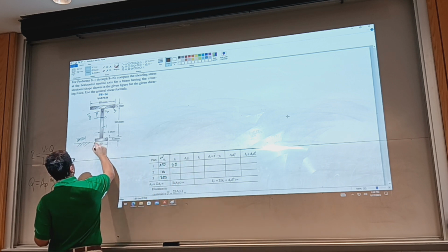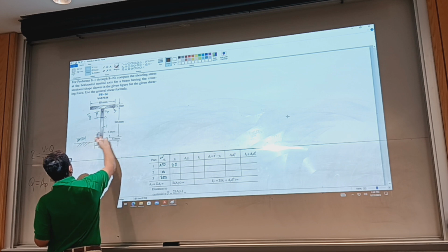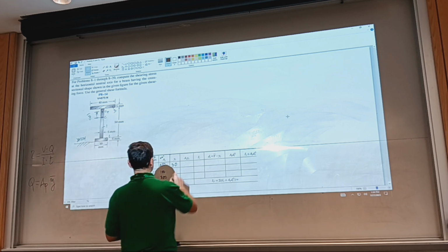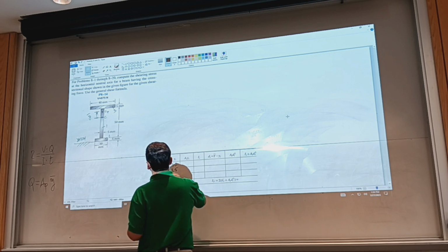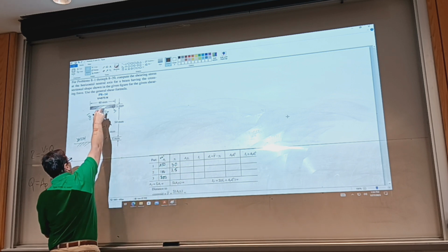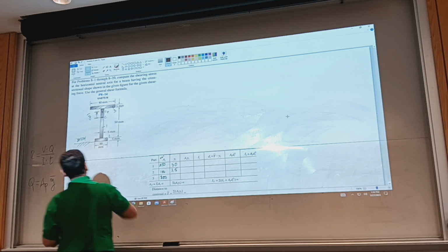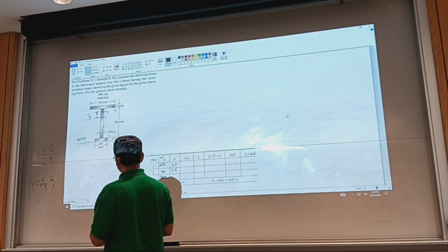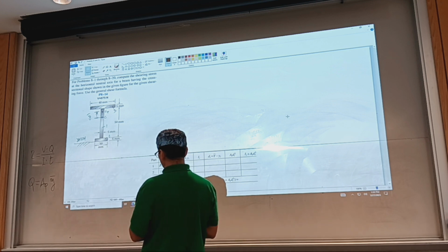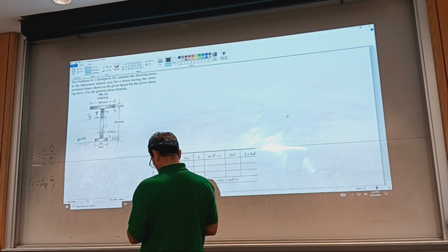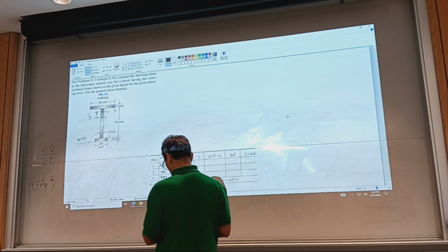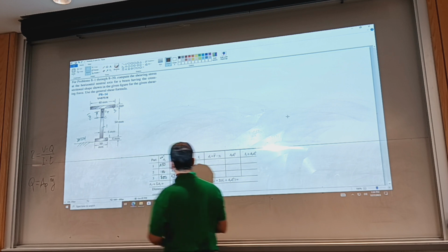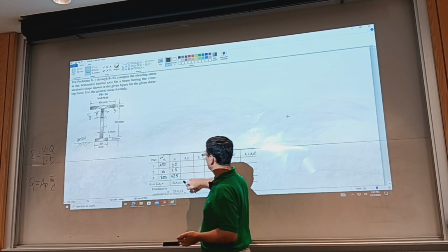For shape 2, the small horizontal rectangle, that's half of 5, that's 2.5. And from the datum all the way to the centroid of the wider flange, that's 50 plus 5 plus 2.5, that's 57.5. Okay, we can now evaluate these products.